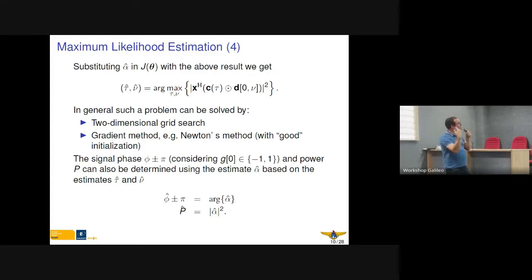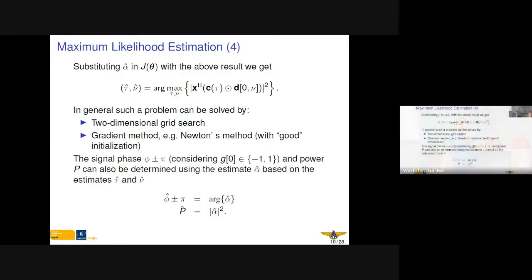And we will create something similar, which is a frequency lock loop or a phase lock loop. And we'll use the Doppler estimate to refine the estimates over time with this phase lock loop or frequency lock loop, and track also the change of the parameters. So of these two bullets that we have here, the first one is perfectly representing acquisition, and the second one is then representing a gradient method, so the implementation in delay lock loop, frequency lock loop, and phase lock loop. And this we will discuss tomorrow afternoon.